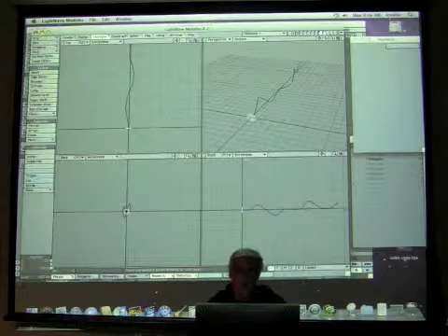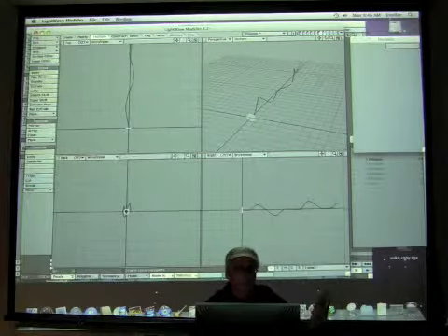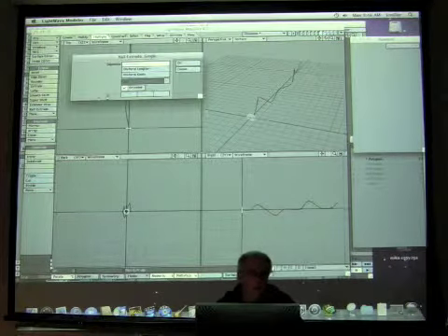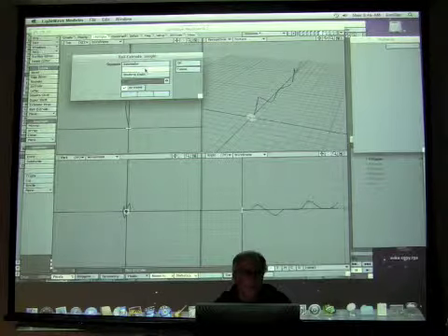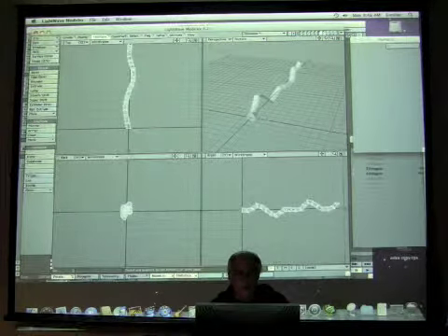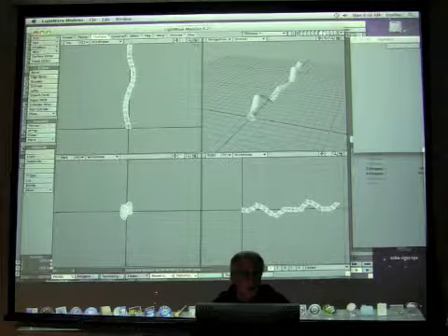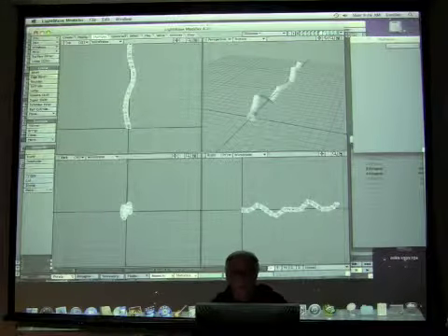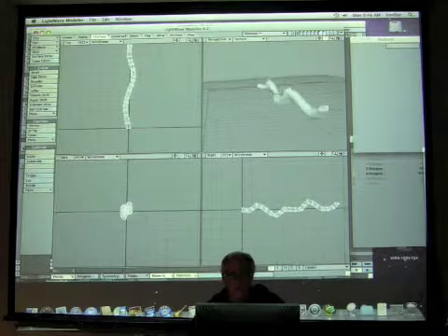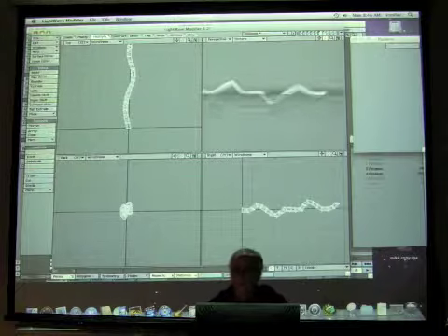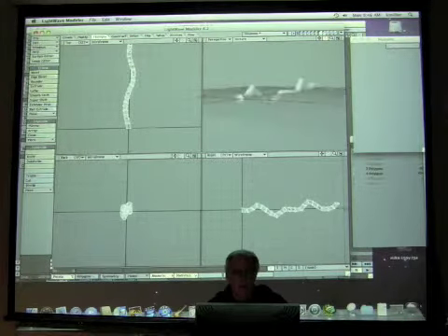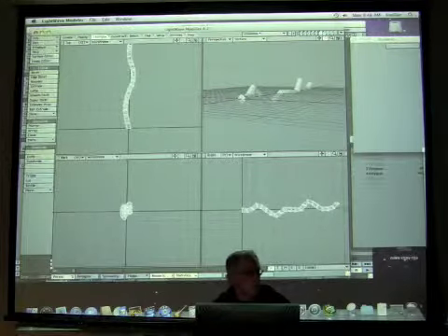Now what if you wanted it to follow the path, but you didn't want it absolutely smooth? Another option would be to rail extrude, and we're going to use uniform lengths. And I'm going to leave the default setting at 20. And you'll see that it basically extrudes this along that path 20 times. And now it looks like a bent up straw, like somebody has taken it and bent it in several places. It doesn't have that smooth, uniform look that it did before.